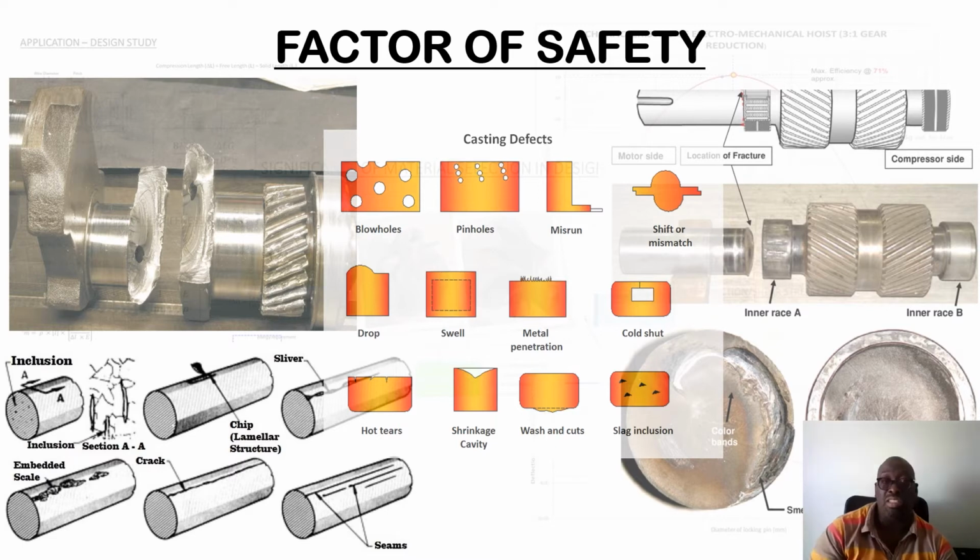There's always that possibility of microscopic defects within the material, probably due to the quality of the material pre-manufacture, or surface defects on the external surface of the material, which could constitute what are called stress risers. And these stress risers more or less amplify the level of stress within those regions where there's a presence of microscopic or macroscopic defects.